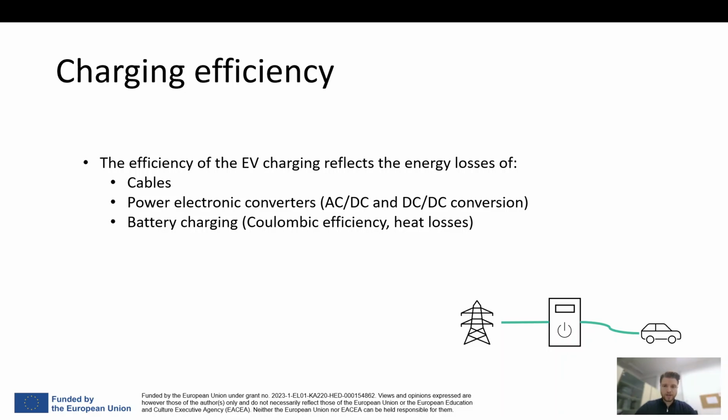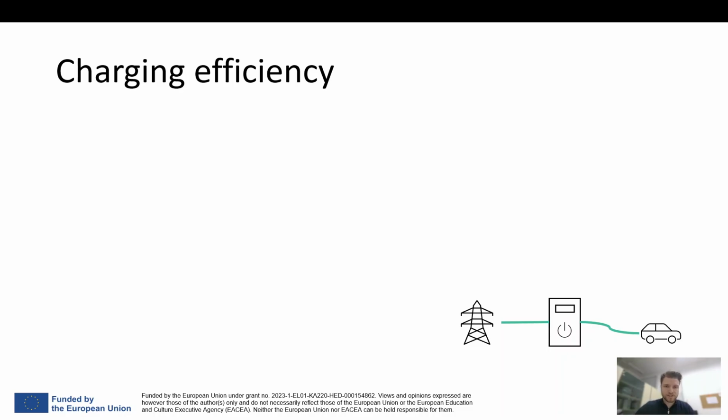This is one form of a loss, but the other form of a loss is the heat loss. Even if the energy accumulated in the battery increases, it is going to have some standby losses because the temperature of the battery also increases, so it dissipates heat to the outside. There are also losses or power drawn from the cooling systems of the battery, and other losses that reduce the energy that is accumulated in the battery that can be modeled as some standby losses of the battery.